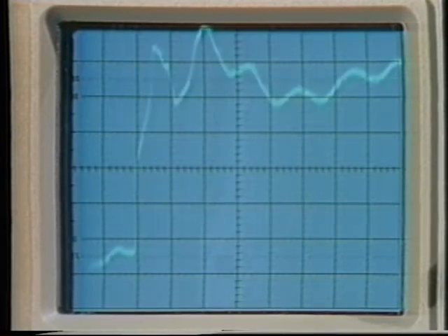Now, if you don't ground it at all, you get this. Pretty, isn't it? The moral: grounding probes is important. Keep your ground lead short. If that's not possible, reduce input capacitance of the probe by using a low Z passive or an active probe.